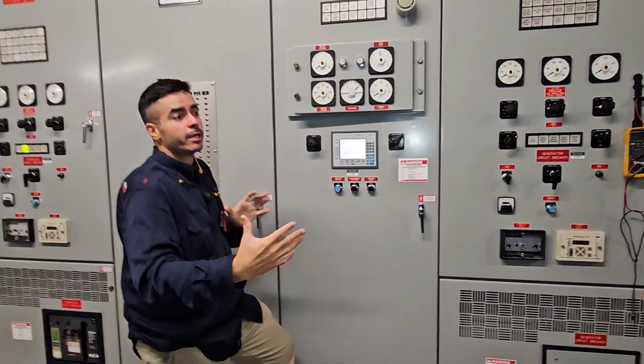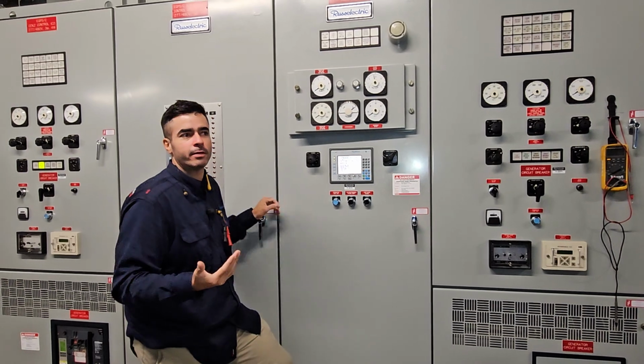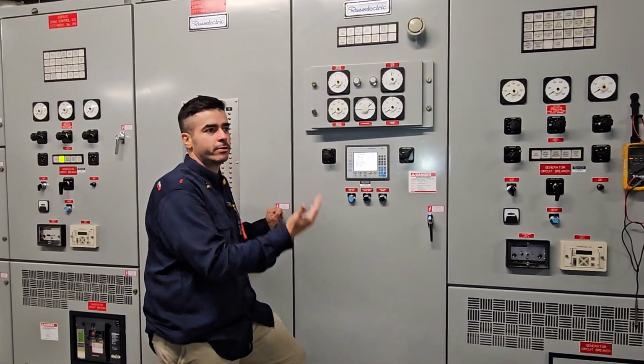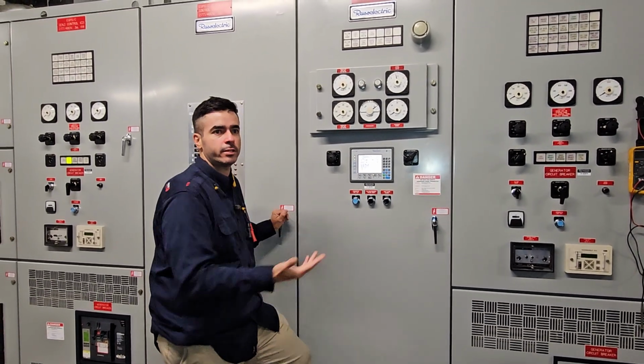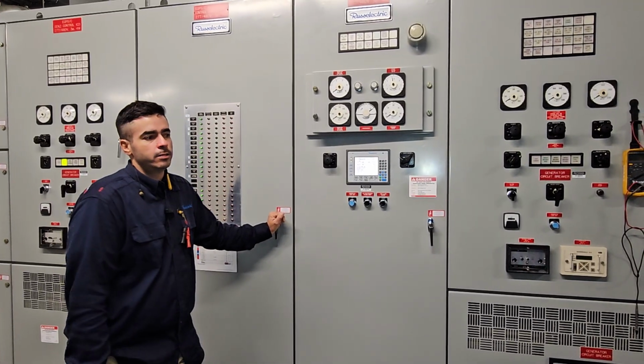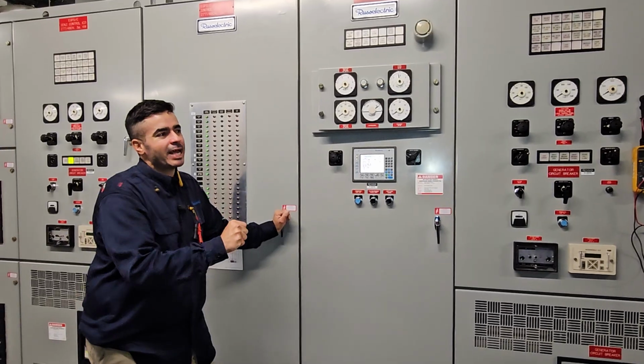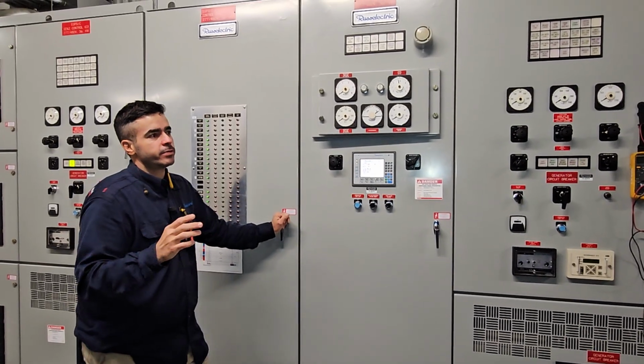But it takes a long time because it has to be in sync, because it can't just do it. If it closes out of phase, you're closing out of phase between generators and utility. That will be a bad situation for the ATS, right? So trying to answer your question, it's not really a lack of time on transferring.